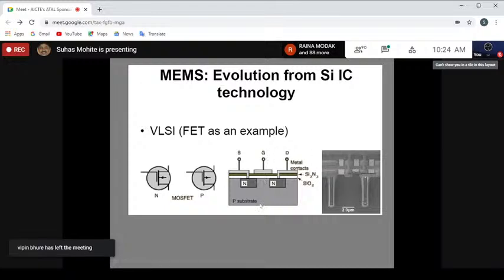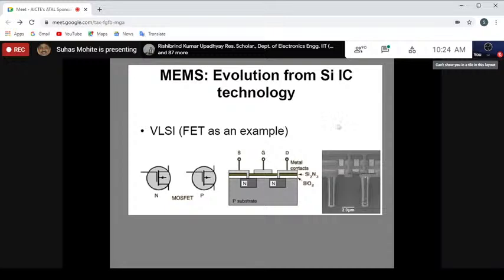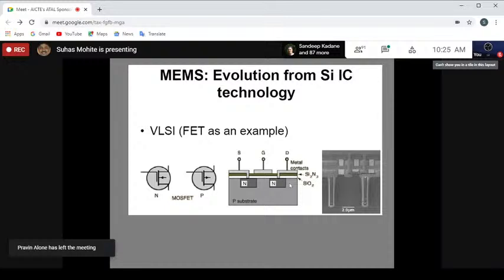The two wells that you can see here, the pentavalent impurity wells, where doping has occurred here and doping has occurred here, and there is a certain gap between these two. This particular gap has reduced by many orders of magnitude, from micro to nano, to a one-digit nanometer length scale. From 10 micrometer to 10 nanometer, that shrinking has taken place, and then the switch has become miniature, and that's why memory size has reduced, transistor size has reduced, the device size has reduced.